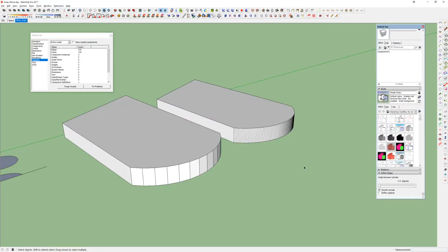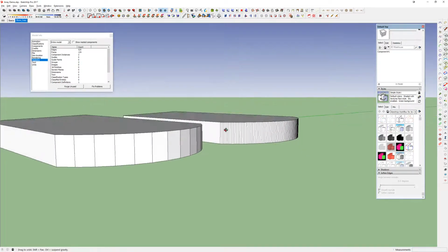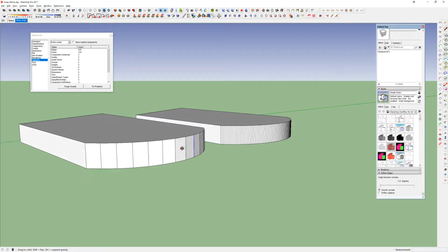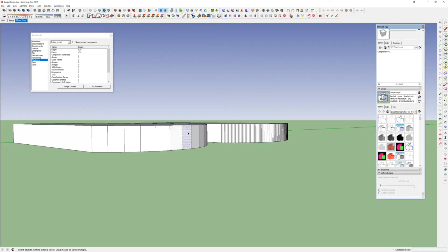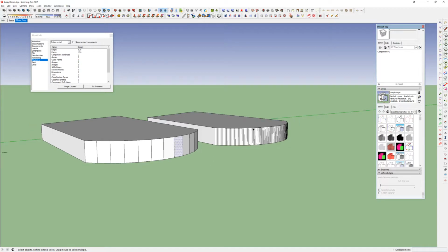But I'm going to knock it down all the way to 0, and those hidden geometry lines are no longer hidden, and you can now see the smoothing is gone because there is no smoothing. The shading becomes very distinct, especially right here in this area, where now with these selected, you can start knocking this up, and this is where your softening comes from.